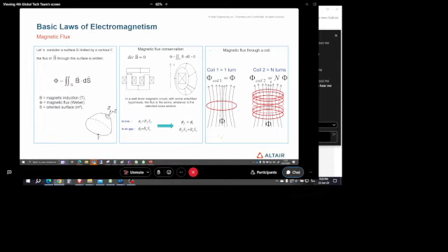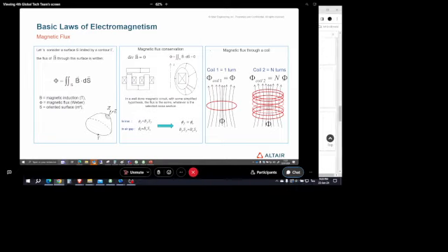If I have a coil with n turns, the magnetic flux I produce with a magnet, something like this, I will recover on the coil n phi, where phi is the magnetic flux I produced, and n is the number of turns. So here, if I vary the magnetic flux, the voltage I am going to have is minus n dphi by dt. And here, the voltage I am going to have is simply minus dphi by dt if I vary the magnetic flux.